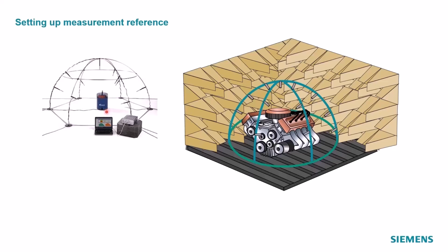That will be in ideal conditions for measurement, like an anechoic or semi-anechoic chamber, and at a certain temperature, pressure, and relative humidity, all of which can play a role. So they give us that, and then to characterize the environment, we can use that same reference sound source in our environment where we measure, and compute the sound power from that and compare it to what has been reported by the manufacturer of that reference sound source. We find the difference between the two and then apply that correction.